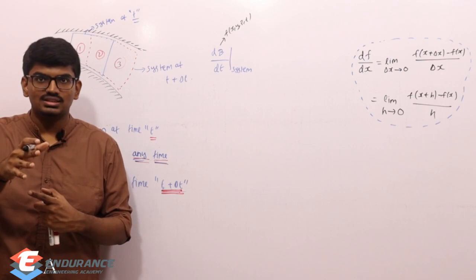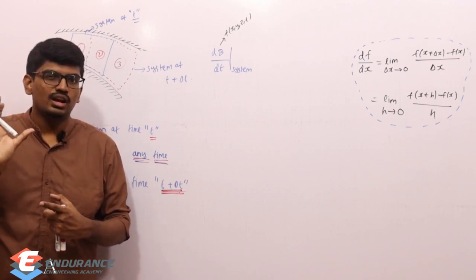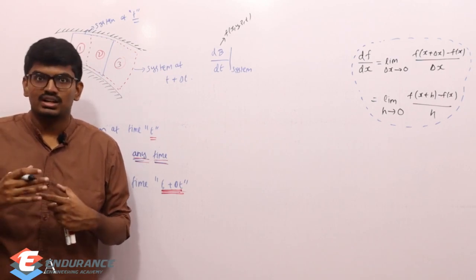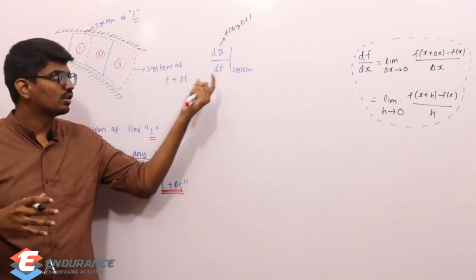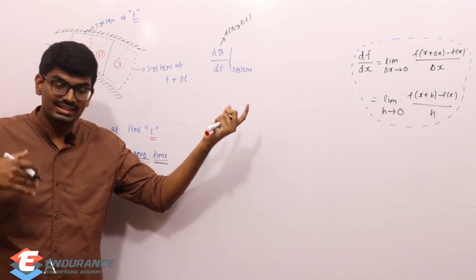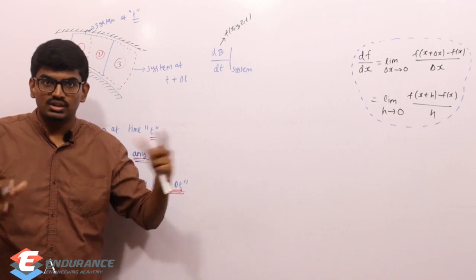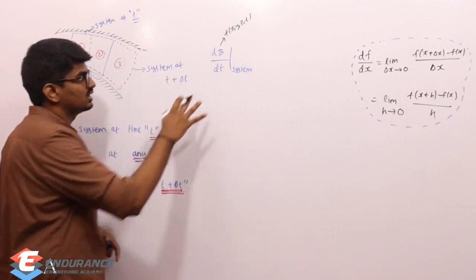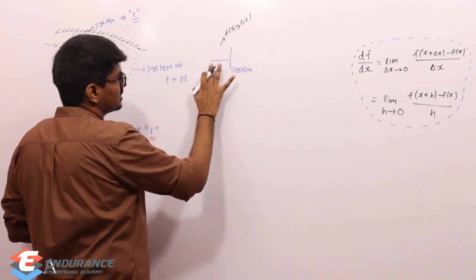If that is the case, then how do we specify the rate of change of a particular property? I already gave this when I discussed acceleration in fluid kinematics. What is that? Material derivative. I should not use the normal derivative because B is not a function of only time. B can be a function of space and also of time. It's a combination of both. So I should not use the small d. I should use capital D. So let me just change it.